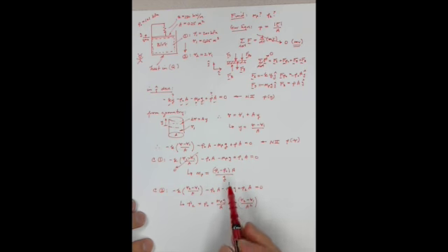Before we move further, just consider what happens when we plug in for the mass of the piston here. If I plug in for the mass of the piston times gravity over area, which is what this term is, I'm going to have P1 minus P naught plus P naught, this just becomes P1 plus K times V2 minus V1 over A squared.